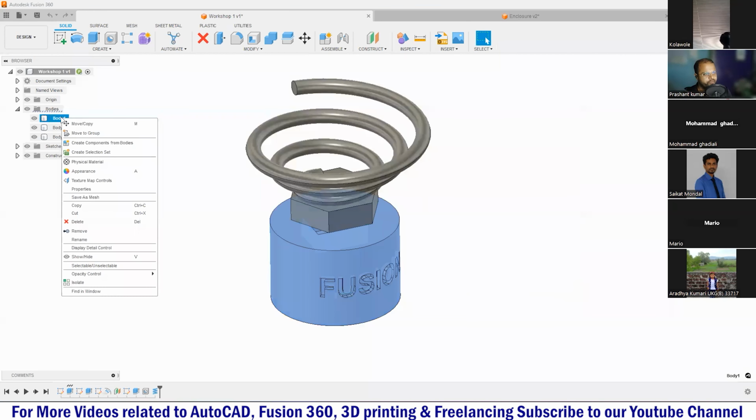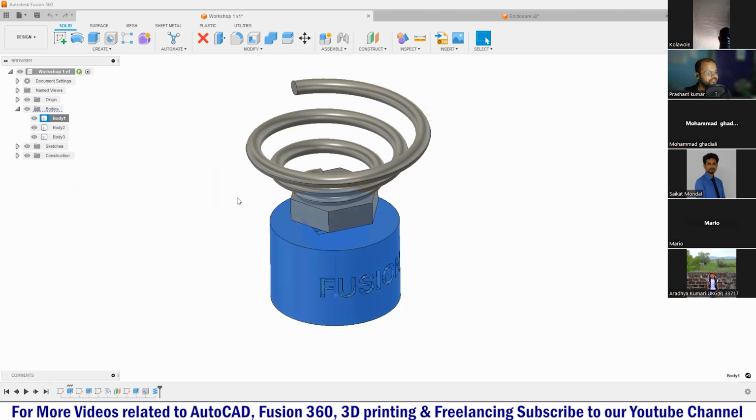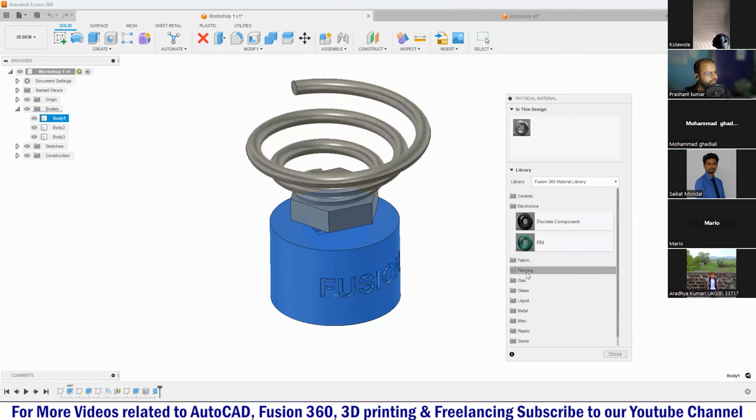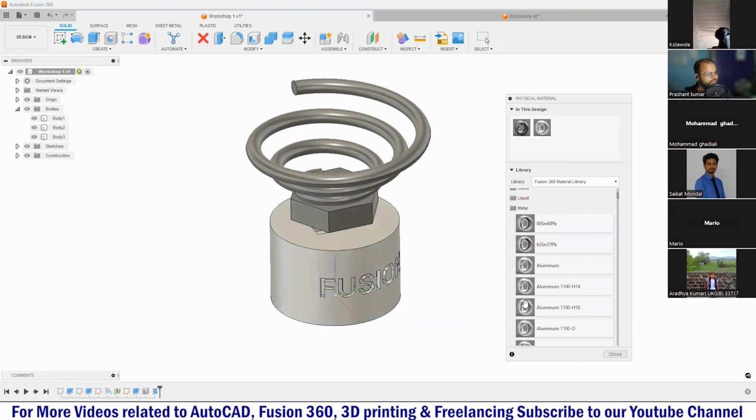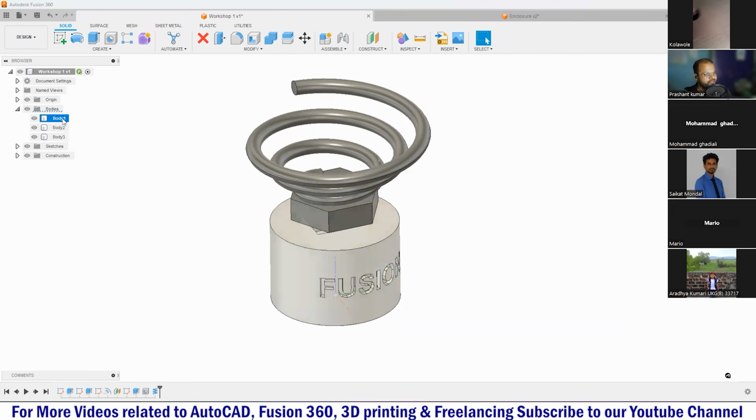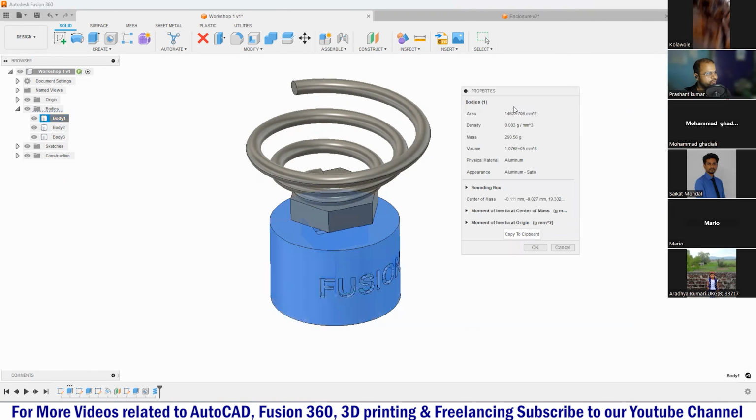But before that, you have to make sure that your physical material properties are correct. Just select your model, right click, click on the physical material properties, and update to the correct material. Then you will be able to find the right information. For example, if I apply some aluminum material for this part and check the properties, now these values are related to aluminum. Like this mass is related to aluminum right now. So these are the properties we can quickly check inside Fusion 360.